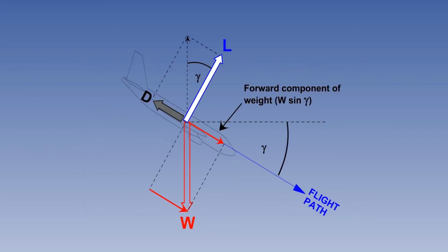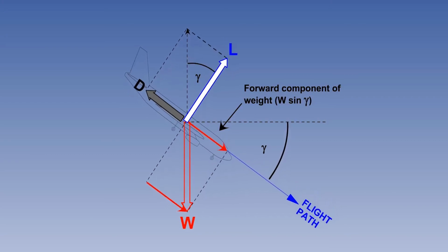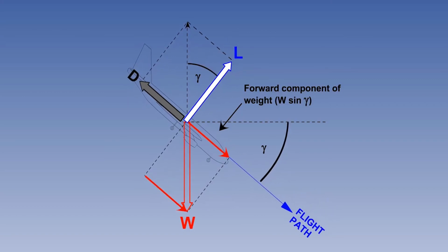The maximum lift-drag ratio of an aircraft will only be obtained in the clean configuration. Extension of flaps, spoilers, speed brakes or landing gear will reduce the maximum lift-drag ratio and give a steeper glide angle, thus reducing glide range.